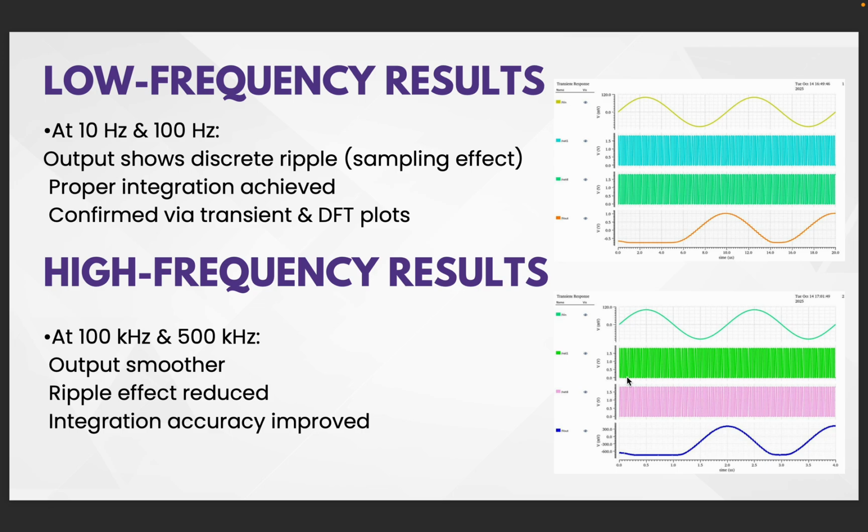As the frequency increased to 100 kHz and 500 kHz, the output became much smoother and the ripple effect was greatly reduced, showing improved integration accuracy.